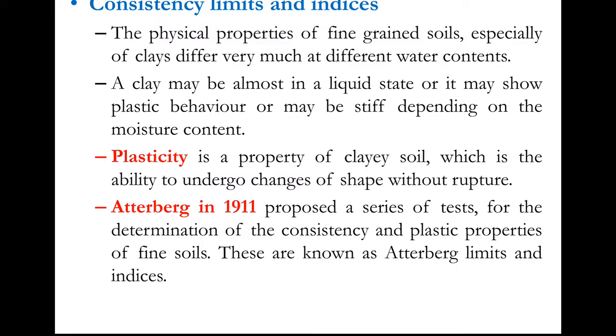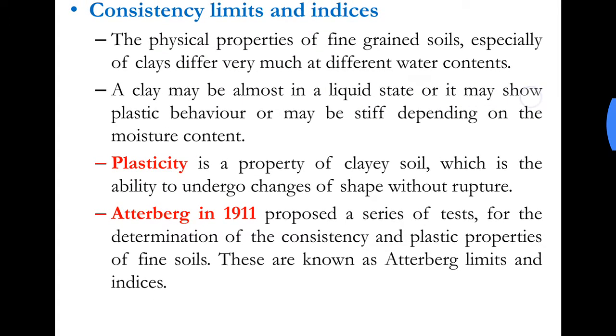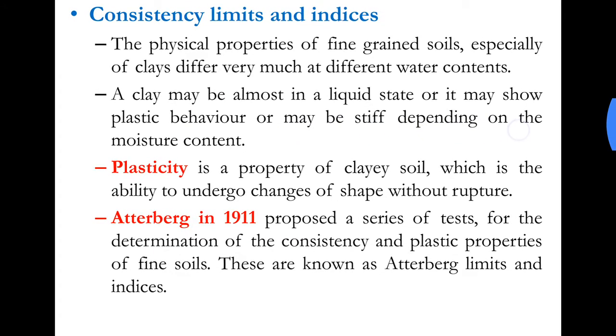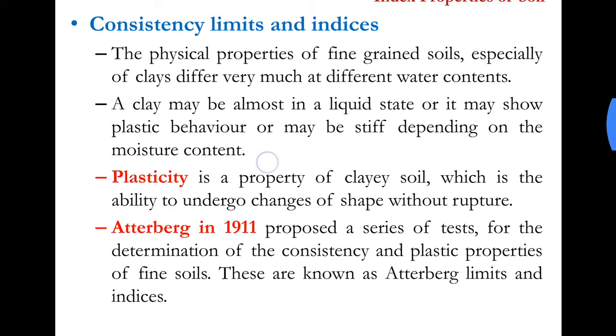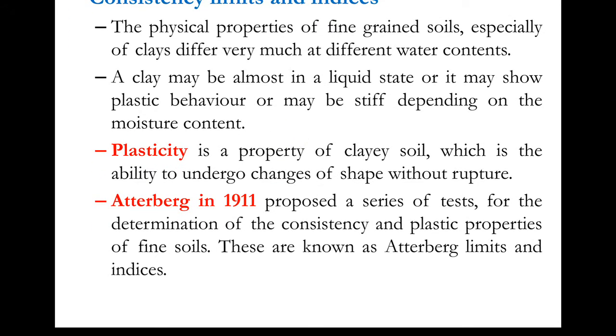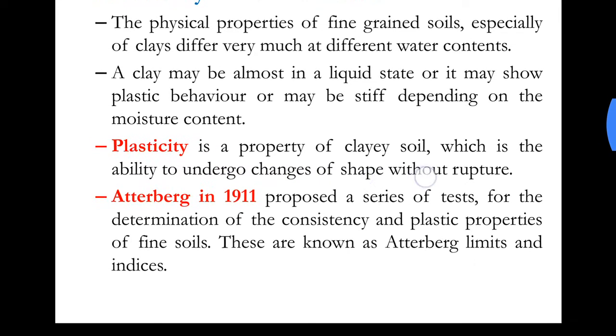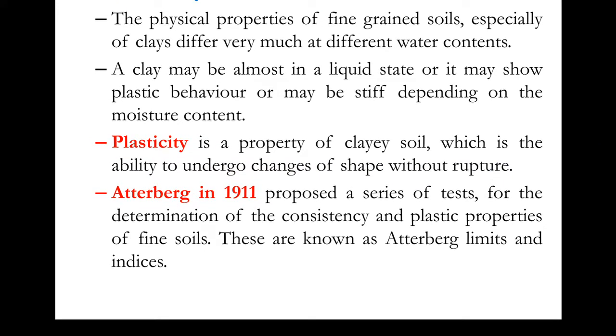A clay may be almost in liquid state, or it may show plastic behavior, or may be stiff depending on the moisture content. This is what I just explained. Plasticity is a property of clay soil which is the ability to undergo changes of shape without rupture. So what is plasticity? It is the property of a clay soil to undergo changes in shape without any rupture, without any cracking or breaking.